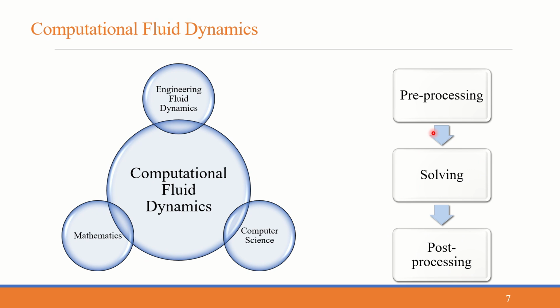After meshing, we will have smaller sized cells. In each of those cells, we will be required to solve for the Navier-Stokes equations, or the equations in our hand, which will involve continuity and momentum conservation equations. But if the problem under our consideration involves heat transfer applications also, those additional equations will also come into the picture. So we will be solving the equations and getting variables like pressure, velocity, and if temperature is involved, those things also.